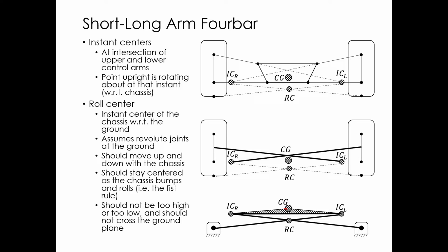So the effect of it is there's going to be an inertial force, an inertial moment, that's going to try to force the car to the outside. It's going to try to make this car roll to the outside. So this would essentially be mass times a_y, or mass times v squared over r, would be the magnitude, and it would face to the outside. So we're going to have this force times this moment arm here, and that's what's going to cause the chassis to roll to the outside.